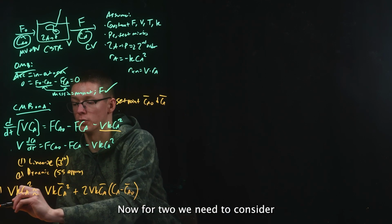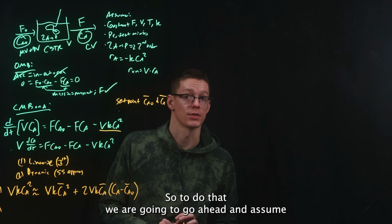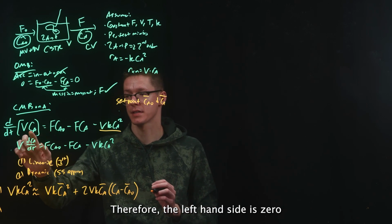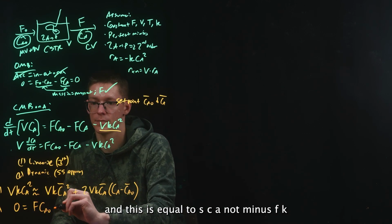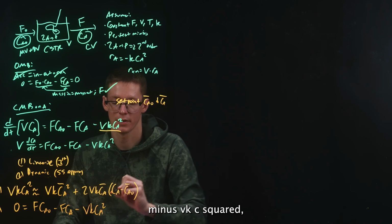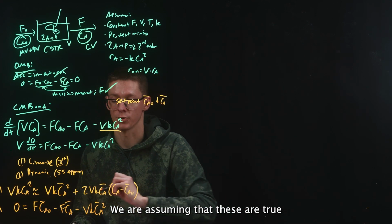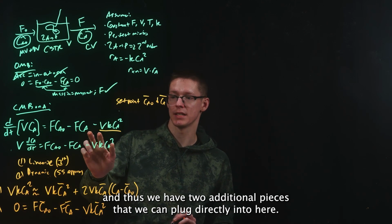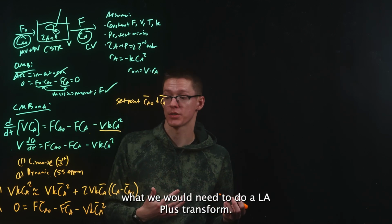Now, for the second, in order to get the dynamic, we need to do a steady state approximation. So to do that, we are going to go ahead and assume that we are at steady state for our component balance. Therefore, the left-hand side is 0. And this is equal to FCA naught minus FCA minus VKCA squared. But evaluating it all at steady state, we are assuming that these are true. And thus, we have 2 additional pieces that we can plug directly into here. We can take this term and generate out what we would need to do a Laplace transform.